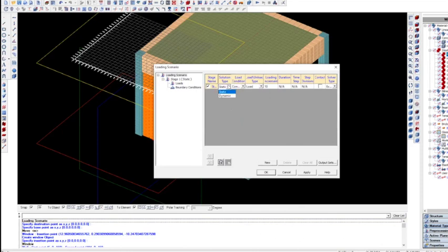For the dynamic loading, you can put here dynamic, and let's keep this as static, and let's create a new stage of loading for the blast. So dynamic loading, of course, you can assign concentrated loads as an impact or displacement, earthquakes, blast loads, uniform pressure, and so on. And so we will speak about the blast loads here. And we are going to assign a very small time step so that we take into consideration the impulsive loading phenomena of the blast loads.